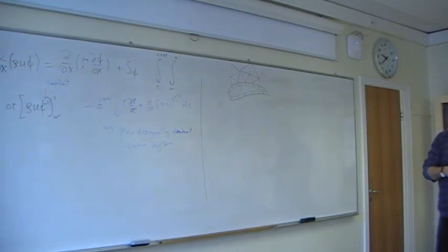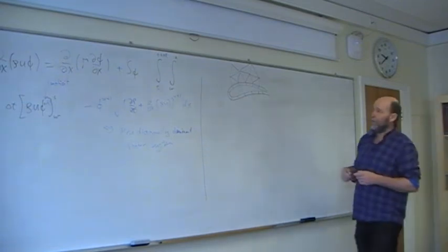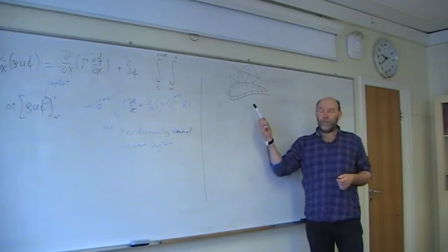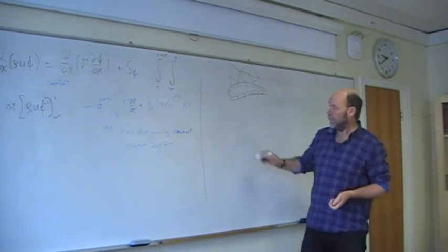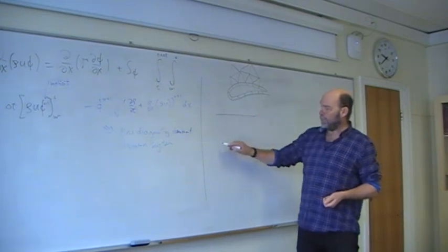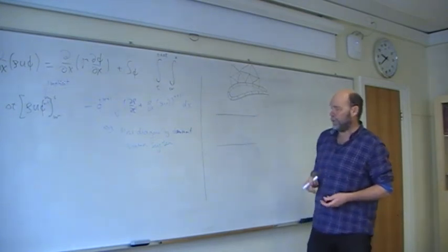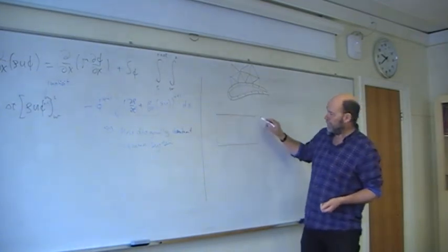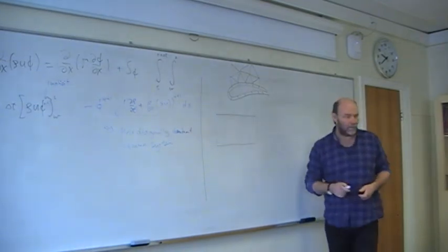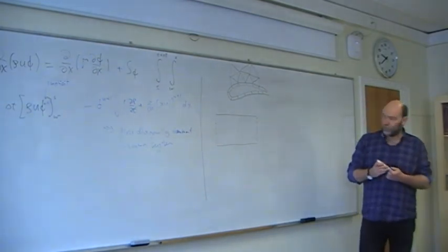So that should be quite possible. And you will have methods dealing with just these problems. But before you do something like this, first a test case. Take a two-dimensional flow between parallel plates. Use periodic boundary conditions, and the flow is laminar. Then you know the solution.